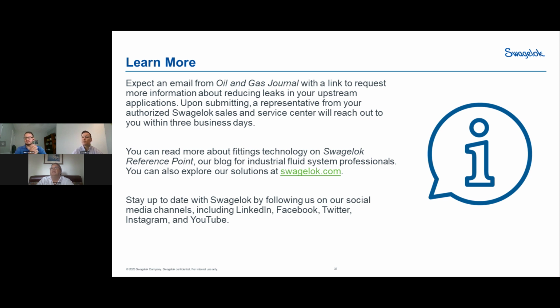Swagelok does numerous testing on those engineered combinations to ensure that the design pressure is correct. We have our own engineered combinations catalog that lists the various alloys that can be used. Usually the tubing design pressure rating is based on the tubing, so it can differ slightly from tubing material to tubing material, even though the fitting stays the same.